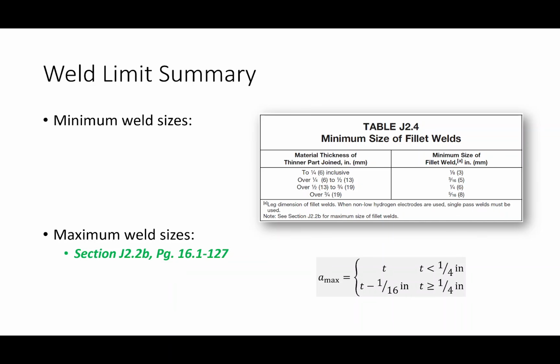What we ultimately need to do is supply enough area of the weld to resist the load, okay? And here's what I'm saying. A bigger weld size results in a shorter weld length, right? Just think, if you've got to supply the same amount of area, if I double the weld size, I can reduce the length by half.